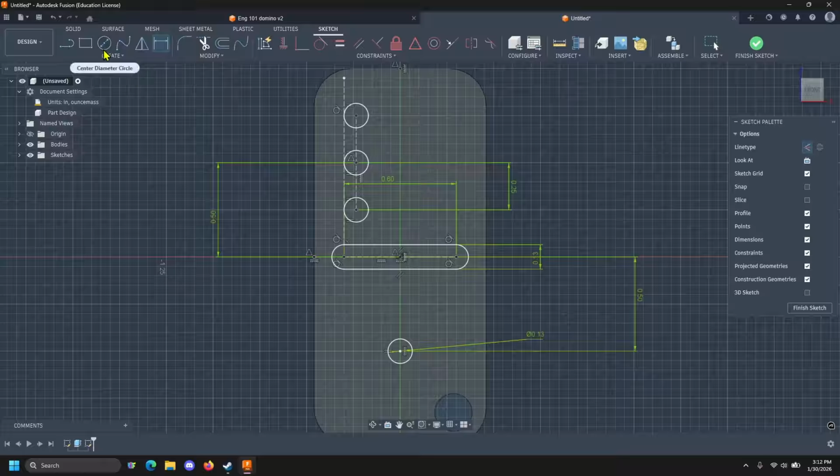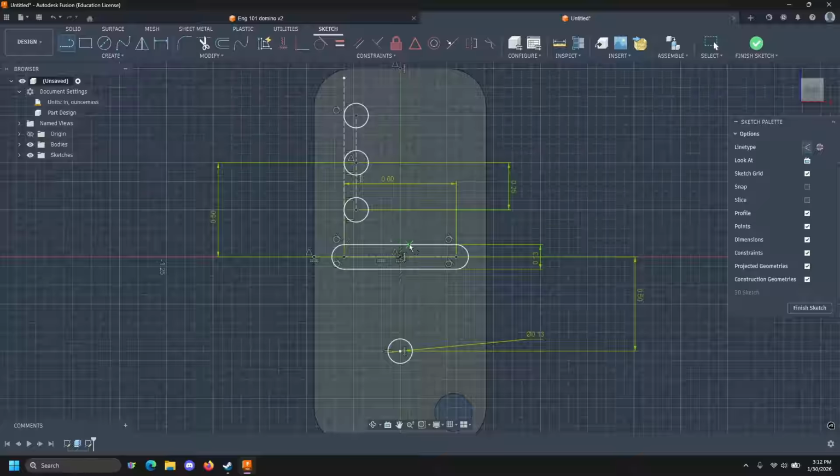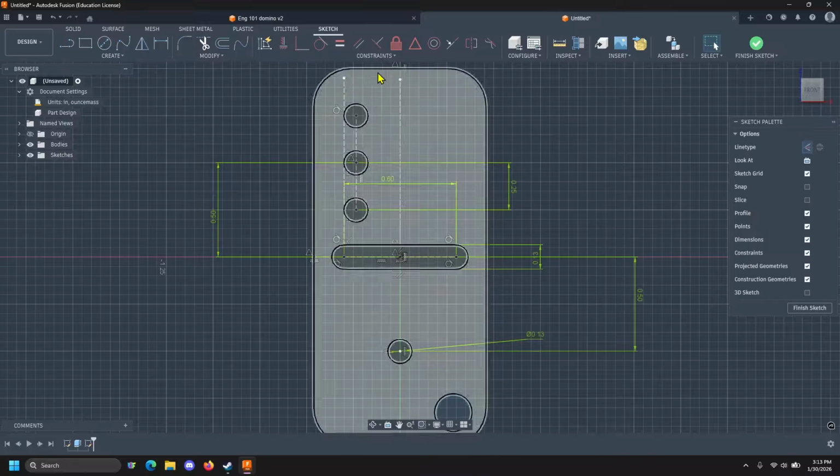The last step I'm going to do for that, I'm going to go back to my handy construction line and find the midpoint. I can just drag the start of my line along till I find the midpoint of my slot, and move another line all the way up to the top. By the way, with construction lines, it often doesn't matter where your endpoints are. It's usually the angle and following along them that matters. So you don't have to worry about these being at the right place. These ends can just be free, as long as it's a vertical line. That's all that matters.